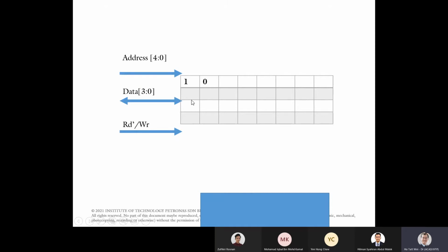So if I want to read this bit, this bit, this bit, and so on, if I want to read this memory in this sequence, it's actually really fast because I only need to do the row access once. All the bits are read out simultaneously into the sense amplifier, and then for the output pin, I'm going to choose using my column address the first bit, the second bit, the third bit, the fourth bit, the fifth bit, the sixth bit, the seventh bit, the eighth bit.